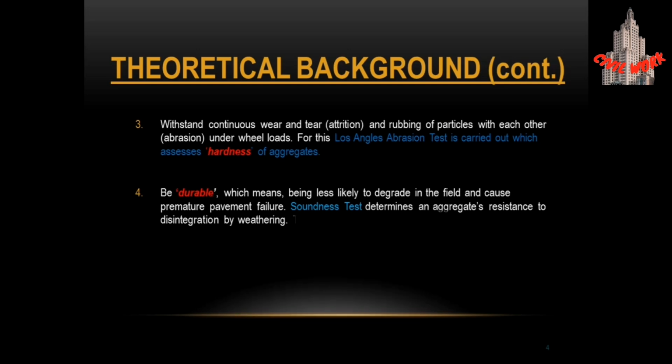Number 4 point is that aggregate should be durable, which means being less likely to degrade in the field and cause permanent pavement failure. The soundness test determines an aggregate's resistance to disintegration by weathering. So for checking the durability of the aggregate, the soundness test is used.